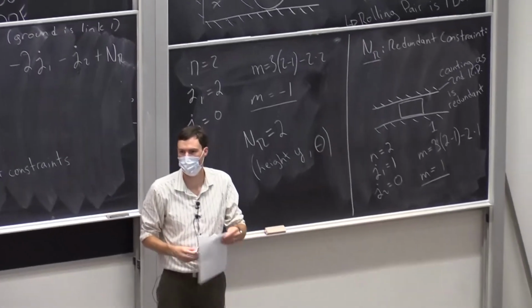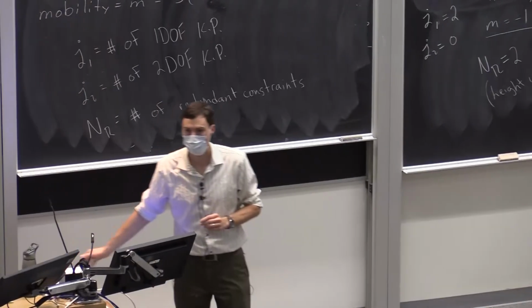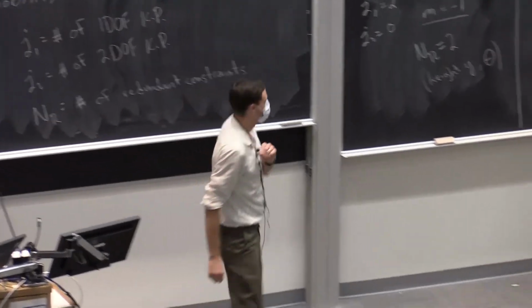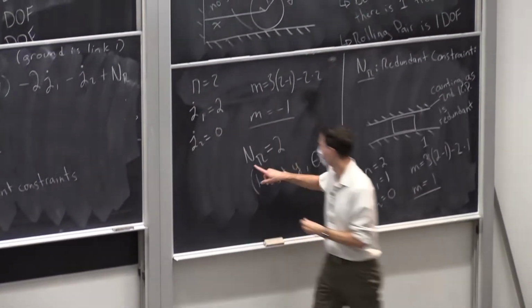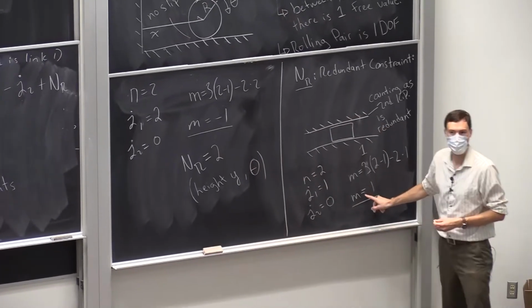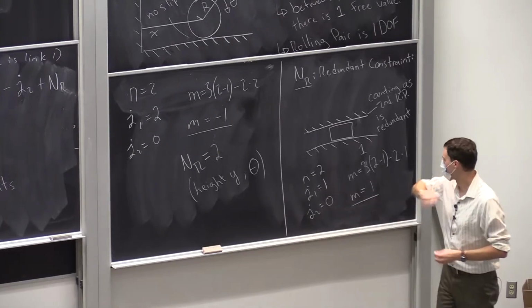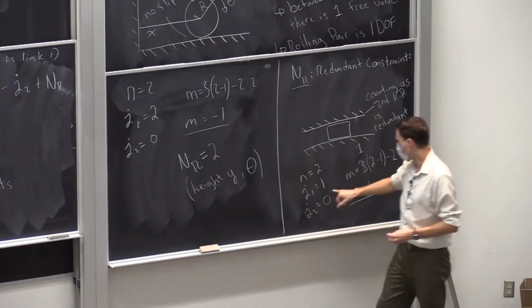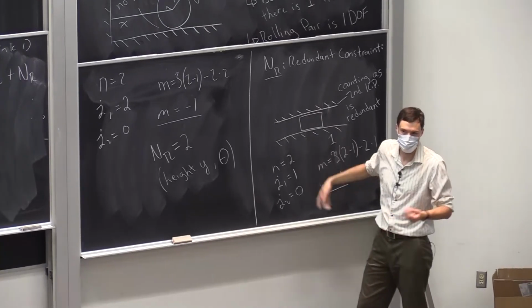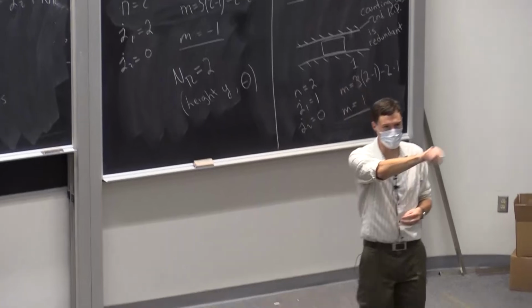Here. Yeah. For the sliding pair, is it only one redundant constraint? It's only one? Number of redundancy, NR, is 2, because the correct mobility should be 1. It can move horizontally. X is a free parameter. So we calculated -1. So to get it back to the correct value, you need to add 2. Okay. You need to add 2. Yeah. Okay, one last question on this?